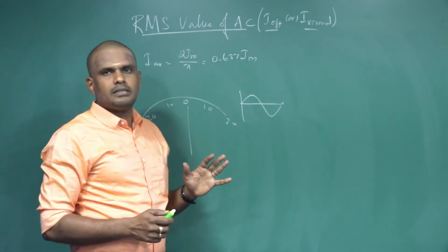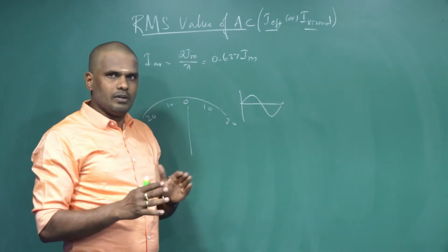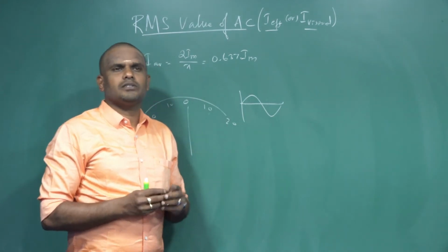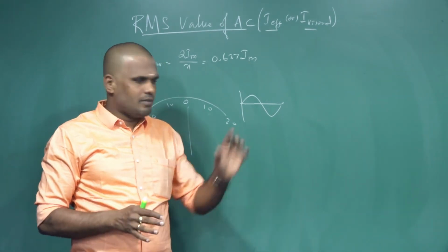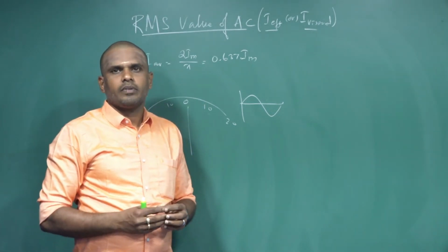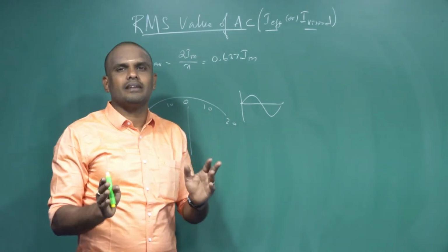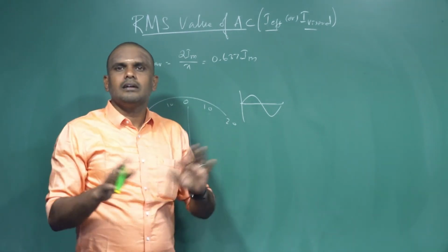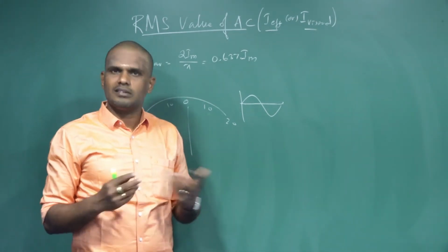So we can simply say here, on what basis the measurement has been done. When electric current is passed through a heating element, whether it is DC or AC, doesn't matter. For the amount of current, heat produced will be H equals I squared RT based on Joule's law of heating. So the direction of flow of current through a heating element is immaterial in this particular case. Whether it is a direct current or an alternating current, the amount of heat produced will be the same if the magnitudes of currents are the same.